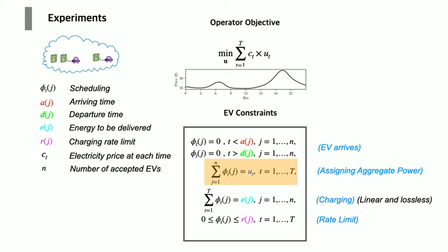As a concrete example of the operator-aggregator coordination, the operator tries to minimize the total electricity cost, and at each time t, the electricity price is a varying value. The charging actions need to be defined to satisfy the charging constraints specified by the EVs. What the operator cares about is the aggregation of total power charged to all the stations. This makes our information aggregation scheme possible.